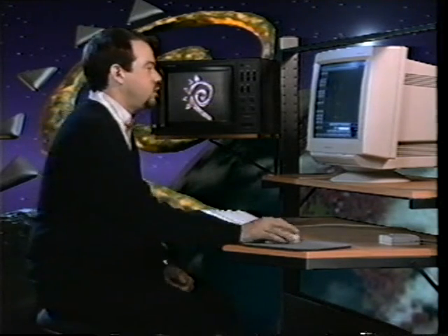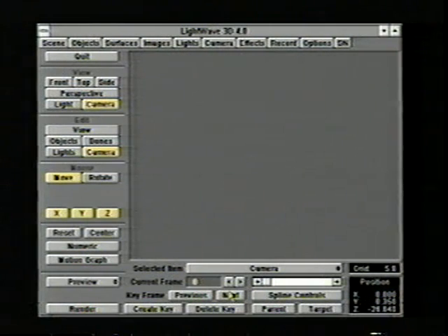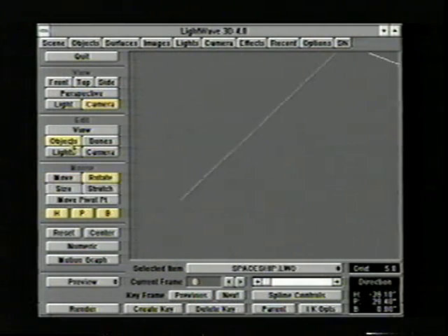So frame 0, even though you don't render that frame in most cases, that's where your items are still parked, so to say. So in most cases, you have a keyframe at frame 0 for your camera, for your lights, and for the beginning of your animation. Let's select Objects. Here, if we select Next, notice we cycle through the frames. We're on frame 60, we're on frame 120, hit Next again, we go to frame 0.